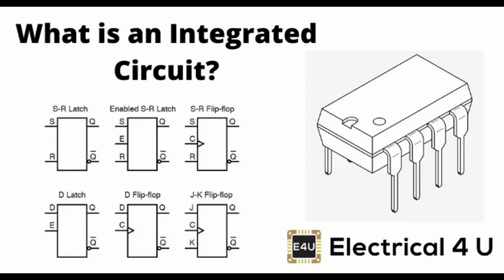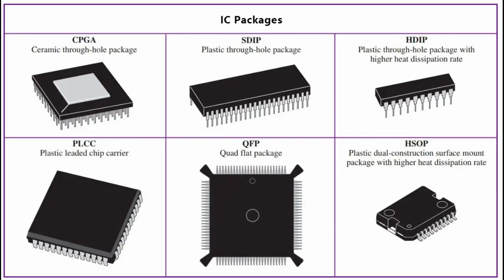Volatile memory. RAM is volatile memory, meaning it loses its contents when the power is turned off. Fast access. Provides fast access to data and is used for temporary storage during program execution. Types. Dynamic RAM, DRAM requires refreshing to maintain data integrity. Static RAM, SRAM does not require refreshing, faster but more expensive.